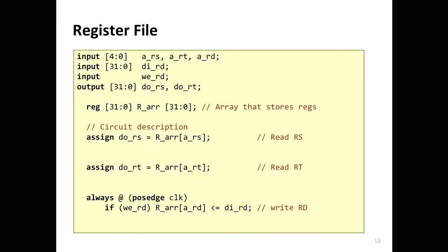And then to implement the register itself, you're going to define an array of registers. And this is how you do an array of registers. How you read this is you implement a 32-bit register and 32 of them. So you have 32-bit data-wide registers, and you declare 32 of them.